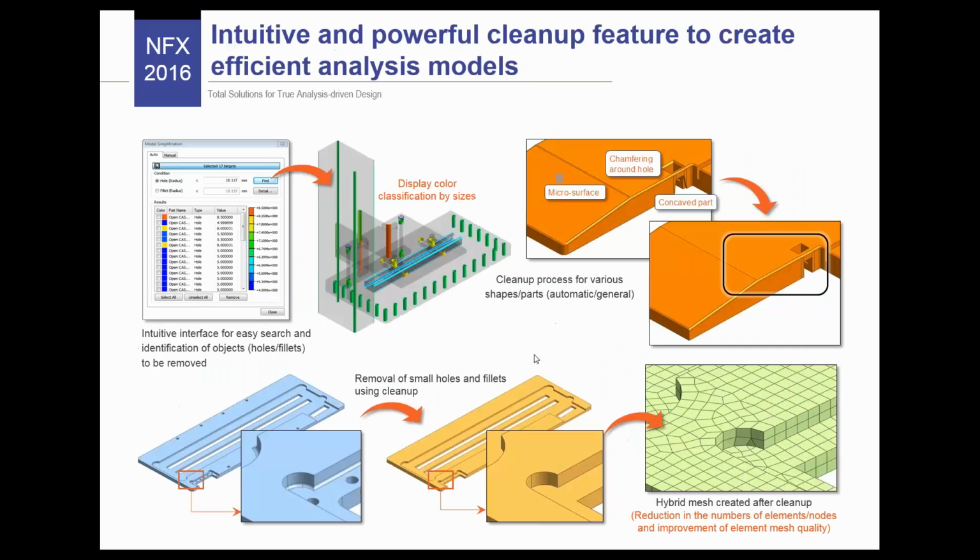So you can import your CAD geometry, you can simplify it, and this is also something very important, and this will be the subject of the first demonstrations by Piotr about the simplification of the model. What happens, you probably know, is that when you have a CAD model, a lot of people put a lot of details inside the CAD models, a lot of fillets, a lot of small holes. All these things actually complicate the simulation when they have no impact on the structural properties of your model.